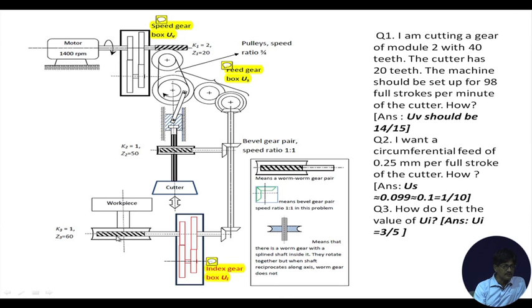So, this rotation ultimately rotates the workpiece, because if you remember, in the gear shaping and gear hobbing machines which work on generation, we have to make the cutter and the workpiece rotate individually, by giving power to them. It is not that one of them drives the other, because the workpiece to start with does not have any teeth on it. So, it has to be made to rotate. The cutter and the workpiece both have to be made to rotate as if they are rolling against each other as fully made gears. That is what we have done.